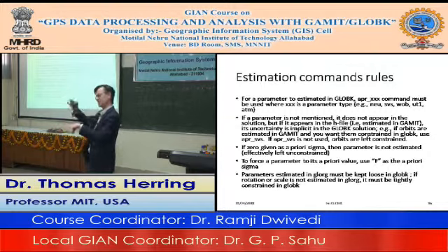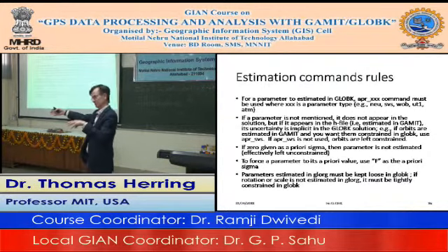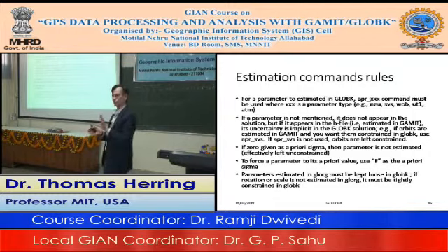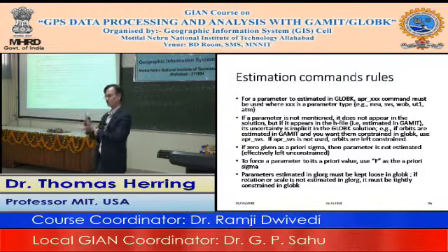It implicitly does whatever it needs to do to be consistent with what's going on, but you just don't know what value it used. This becomes important if you were to do a relaxed solution in GAMIT, where you're estimating satellite orbits, and say you did 5 networks. If you did not use the APR SVS command to explicitly estimate orbits, each one of those networks would literally have its own separate orbit determination. It's by putting in that explicit estimation of the orbits that tells GLOBK to link those parameters together.